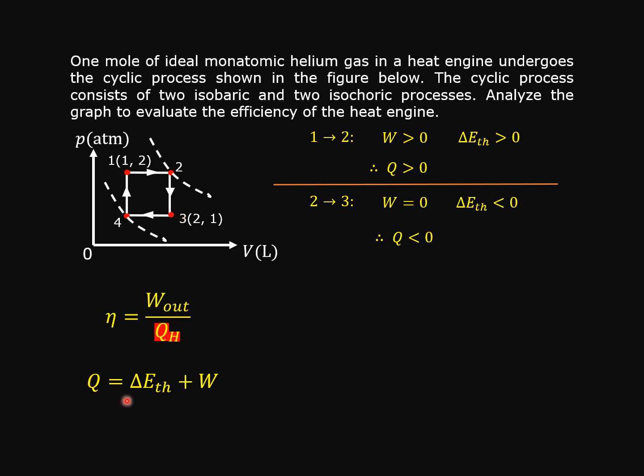So again, apply the first law of thermodynamics. Since W is 0 and the internal energy change is a negative value, then of course Q would be a negative value. So in this process, the heat flows out from the system, or from the gas.